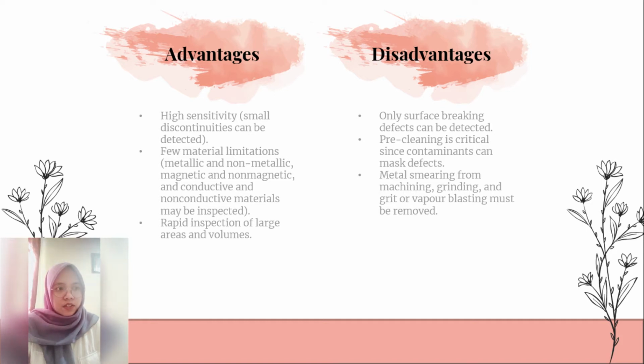The disadvantage of this method is that only surface breaking defects can be detected. Pre-cleaning is critical since contaminants can mask defects. Metal smearing from machining, grinding or grit must be removed.